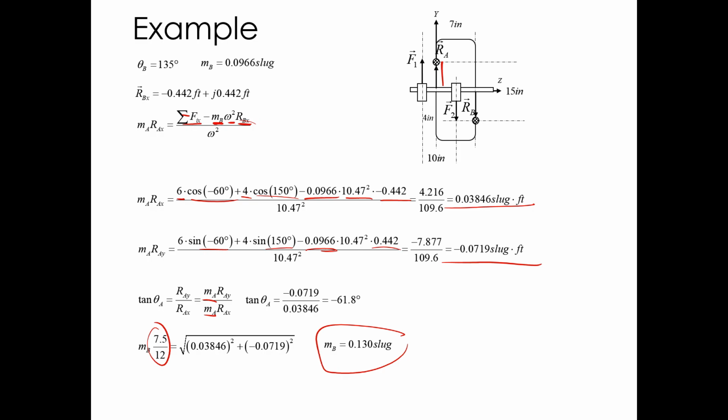Some practical considerations. For tires, they're going to deform as they spin faster and their balance is going to change. So you probably would want to balance these things somewhere around the mean angular velocity for a tire. That might be somewhere around 500 or 600 RPM, maybe higher, maybe lower, I don't know. But that would be the best way to ensure that it would be balanced. Or if you wanted it to be balanced at highway speed, take 70 miles an hour, turn that into the RPM for the tires. And if you balanced it at that speed, it's going to be balanced.